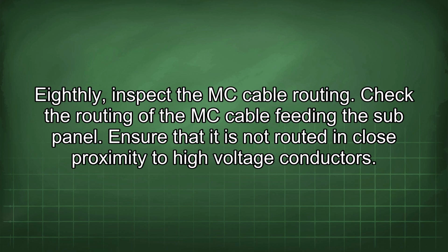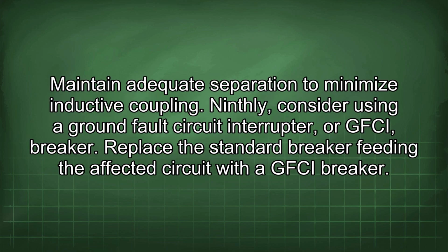Eighthly, inspect the MC cable routing. Check the routing of the MC cable feeding the subpanel. Ensure that it is not routed in close proximity to high voltage conductors. Maintain adequate separation to minimize inductive coupling.